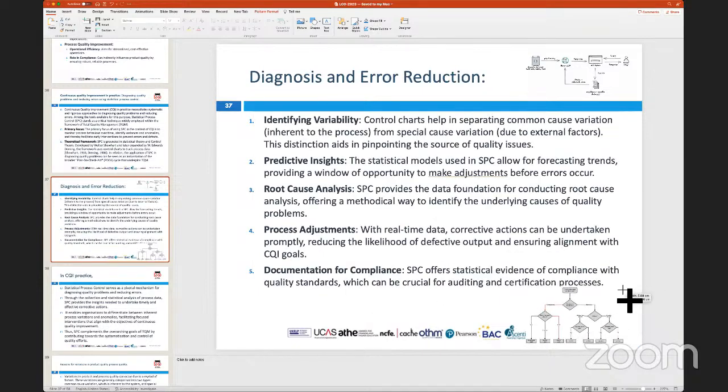So these tend to be done through what is called statistical process control, SPC, and that is where this is quite useful and important, because data helps you to understand variability. Data will help predict certain insights, because if there is variance, and that variance is highlighted over a period of time, that would allow quality managers to detect it and then look at why these faults are happening.